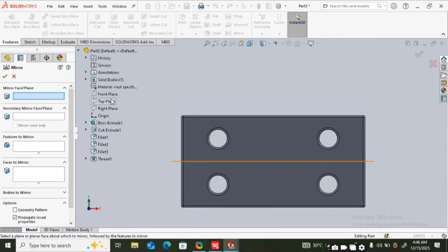If you can recall from our last period, if you want to mirror in sketch, we have to draw a line in the middle. That is, the distance from here to the middle will be the distance from that middle to the plane where you want the model to be situated. So the plane will serve as the line. You don't need to draw a line. The line will not work in this function. It's only the plane that we're going to work with.